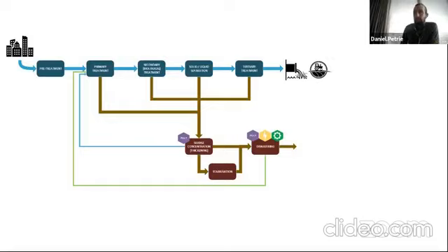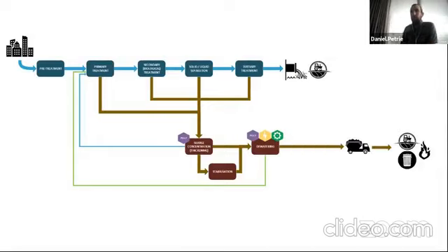So once you've got a nice stackable dewatered sludge, you can transport it off site, either to a landfill if it's hazardous, or it can be applied to land if it's stable, or it can be incinerated if you are in need of a cheap heating source.